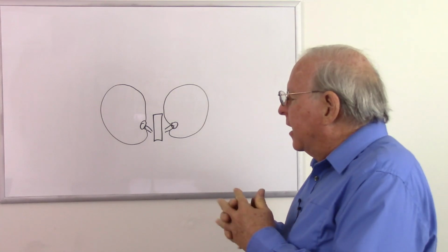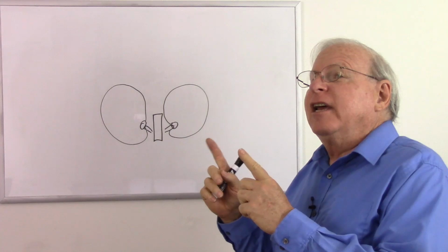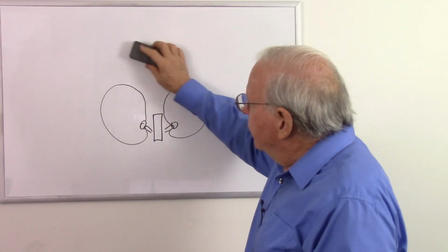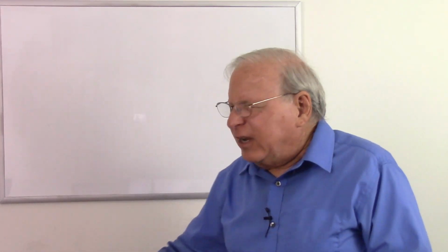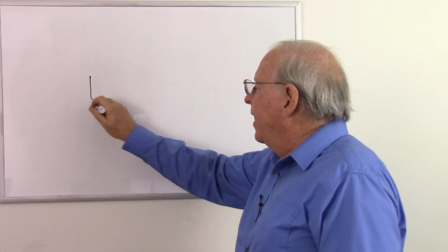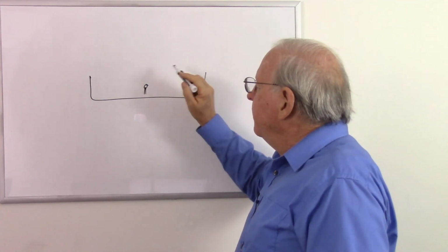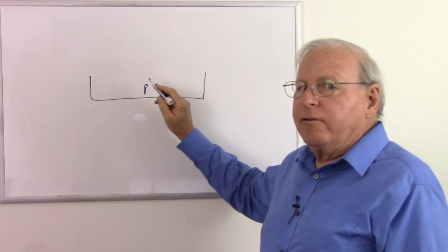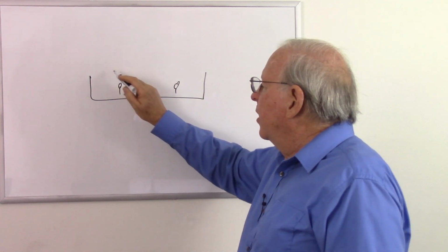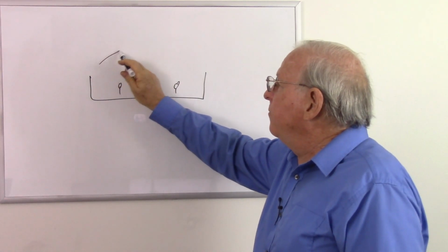One thing that keeps coming to mind that can really mess up your stereo separation is if your microphones are arranged such that some sounds come out 180 degrees out of phase. Because what that's going to do is make the sound, you can hear it, it doesn't completely get rid of it, but you can hear it, but you can't tell where it is. So once again, we have our orchestra here. I'm not going to draw all the instrument names this time, but we have all of our instruments around there. And let's say you have one instrument that's being picked up in one microphone here and one microphone there, and it's 180 degrees out of phase. You will not be able to tell where that sound is coming from. It'll sound like it's coming from everywhere.